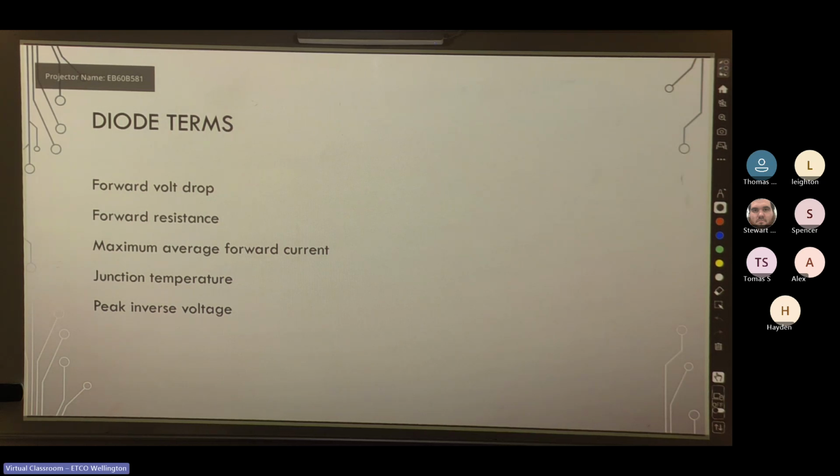Cool. Junction temperature. It's the temperature range the diode will operate normally within, typically anywhere between negative 55 to 150 degrees C. So you're not likely to go past this unless you pile on the insulation inside of a roof space and sandwich the driver inside and then maybe also put it inside a grow room.